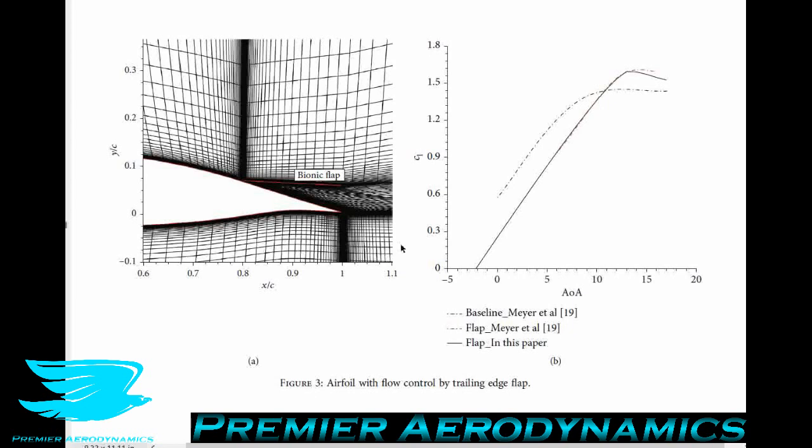And that is also hard to mesh as well, because when you get to the trailing edge, you now have these two cells that have to meet up over a very discrete and small change in thicknesses. So if you have a slight thickness to the flap, that could then mean that you have to have very fine cells around here. So the researchers did quite nicely with this mesh here, I think. But anyway, let's talk about the general effects of this flap.